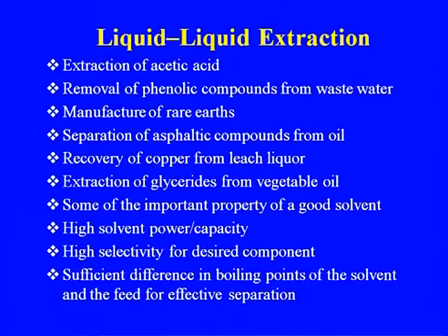Now NMP, sulfolane and dimethyl formamide are some of the solvents which have been developed and are finding wide application, because earlier we used phenol and furfural as solvents. Other applications of liquid extraction are extraction of acetic acid, removal of phenolic compounds from wastewater, manufacture of rare earths, separation of aromatic compounds from oil, recovery of copper from leach liquor, and extraction of glycerides from vegetable oil.